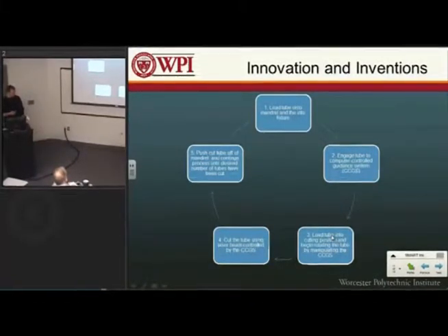And then we will be able to cut the tube, and after we cut the tube, we would push the tube off by moving the original tube back into the new loading position, and that will slide off the tapered end into another device. And then this process will go on and on until you get the desired number of cut tubes that you need for manufacturing or for your assembly.